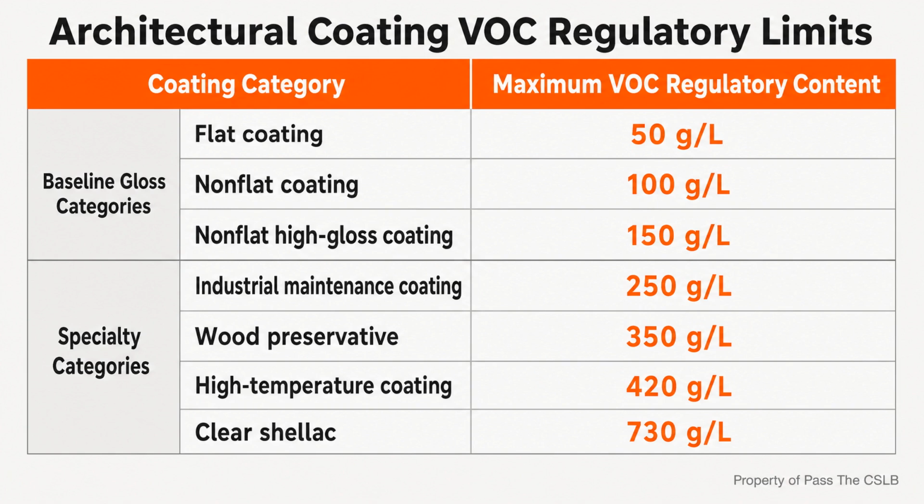Adhesives, sealants, and caulks follow a different regulatory path. California Green points to the applicable air pollution control requirements in the South Coast Air Quality Management District adhesive and sealant framework, with the more stringent, applicable local or regional rule controlling where required. Adhesive limits depend heavily on the application and the substrates being bonded.